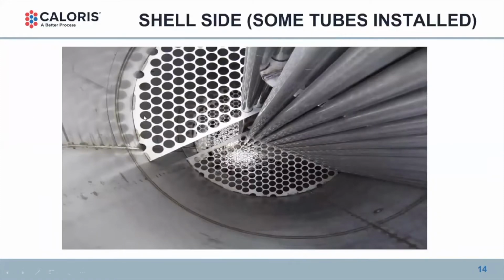And again, here I'm showing the inside of this tube and shell heat exchanger. Typically we're bringing our steam, our saturated water vapors, into the middle, and those vapors need to flow horizontally plus up and down the length of this shell and tube heat exchanger so that we can distribute those steam vapors across all of those tube surfaces and take advantage of it.